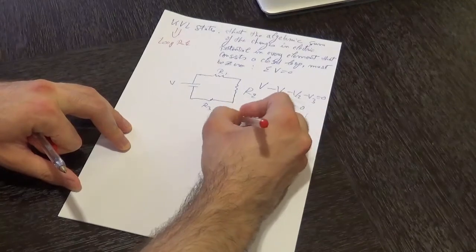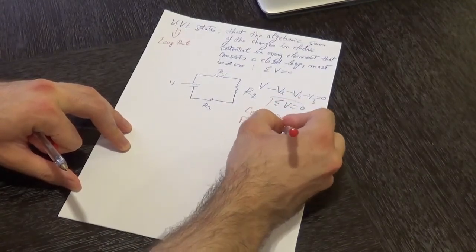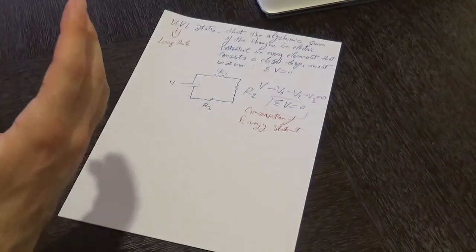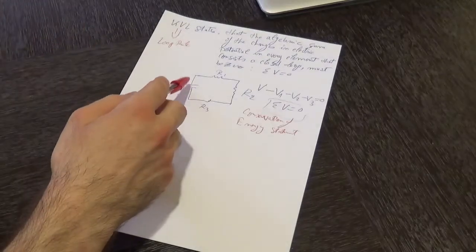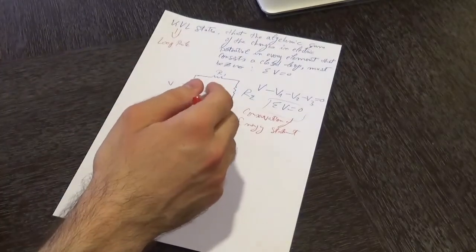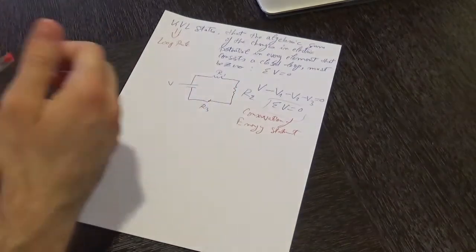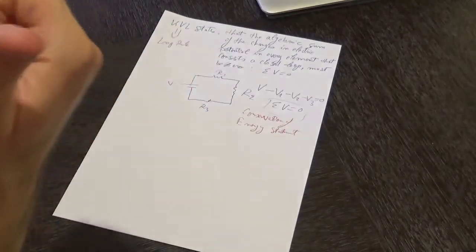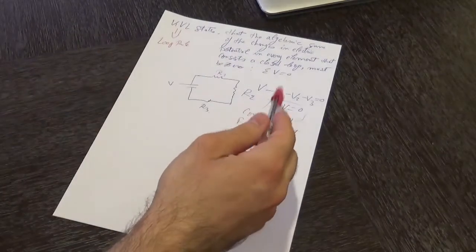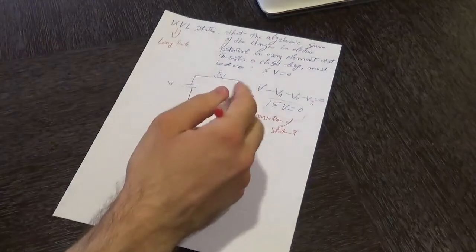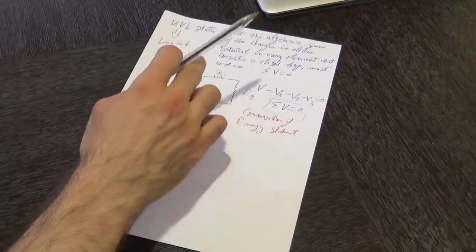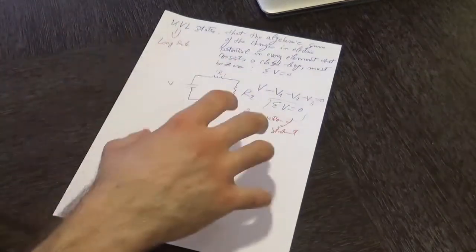So that equation is a conservation of energy statement, meaning that the energy within a closed loop should be maintained or conserved at all times. So the voltage which is being supplied by the battery is being entirely distributed across each electrical component that consists a closed loop. So we don't have any deficiency in energy, neither any excess in energy, but rather we have a conservation of energy within a closed loop, meaning that the summation of all the voltages is equal to 0. Now over here you might be wondering how we have actually chosen the signs for the voltages across R1, R2 and R3. We are going to tackle that topic in a bit.